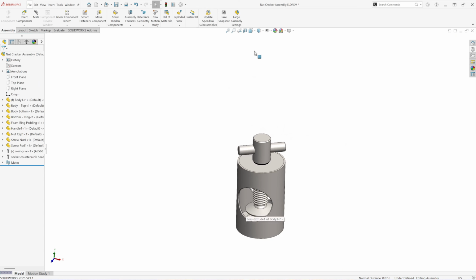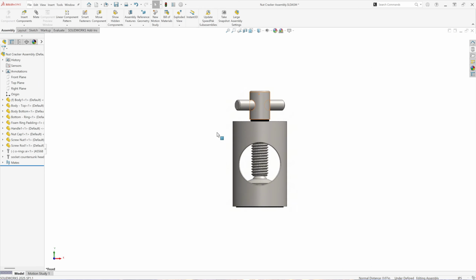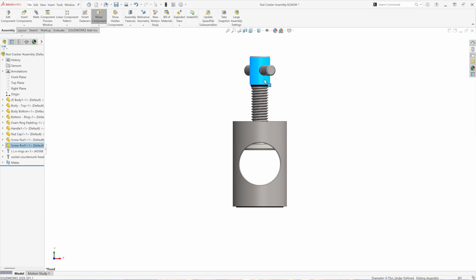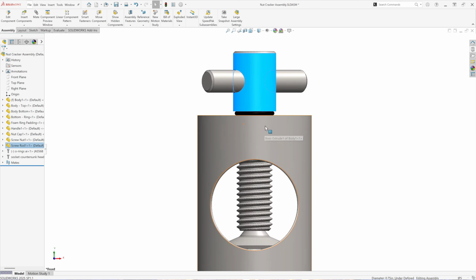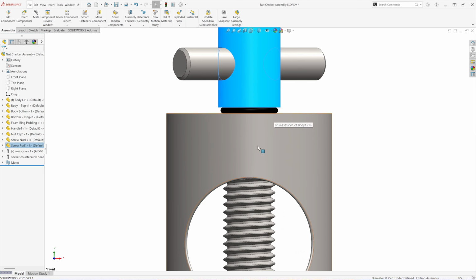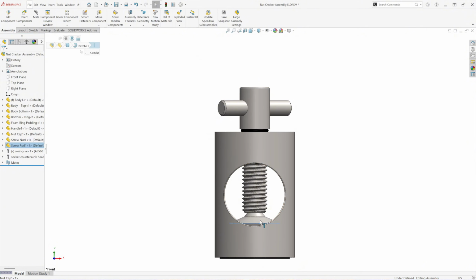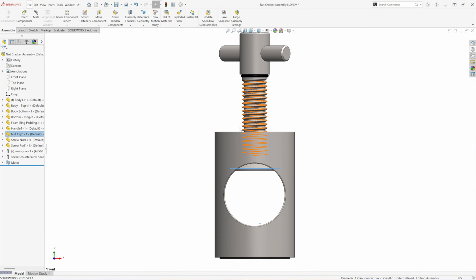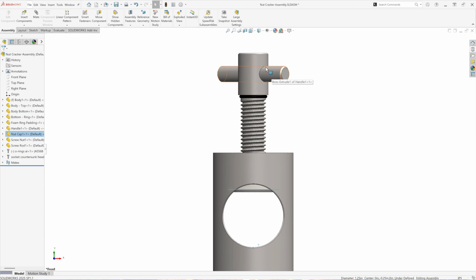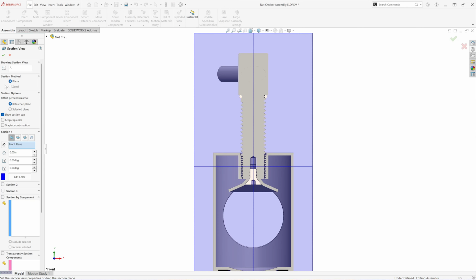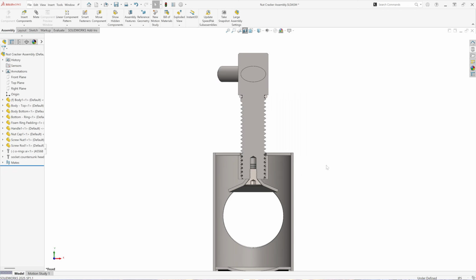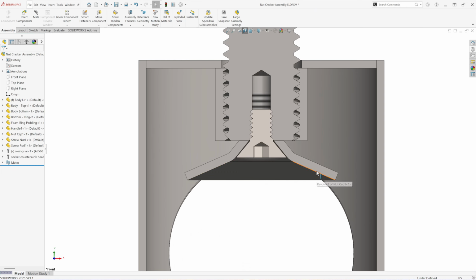I'm going to try it out. I'm going to go to the front view. Okay, so it's stopping at the minimum value distance here, 70 thousandths of an inch. And the travel should be 1 3/8. The maximum distance travel is 1 3/8. So I'm going to go to section view to take a look at that. Okay. And it is.